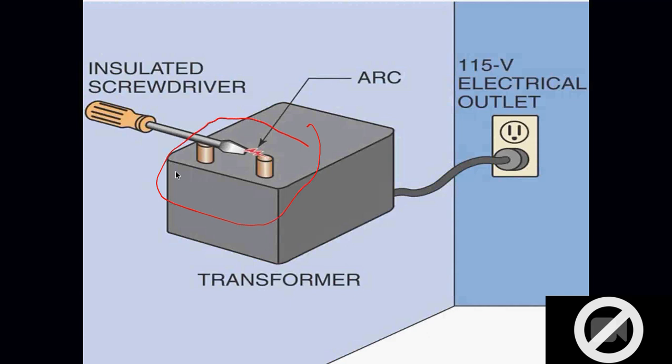So the best way to check this is, you can buy it at a local supply shop, a transformer checker. It's like your voltmeter, and you can clamp it onto the leads, and it will tell you if the transformer is good or not.